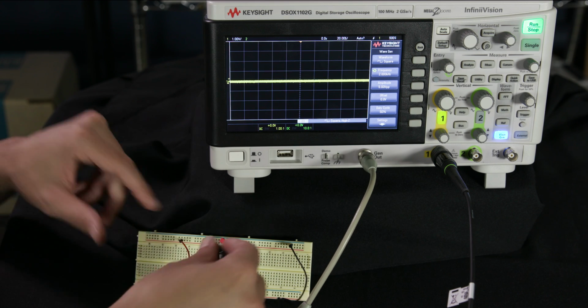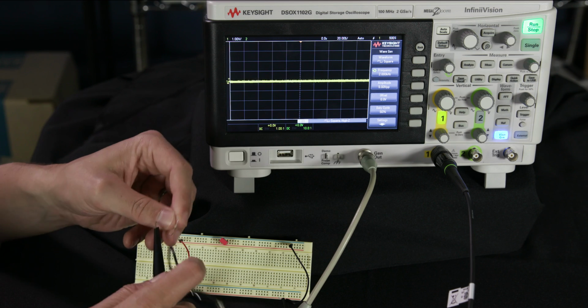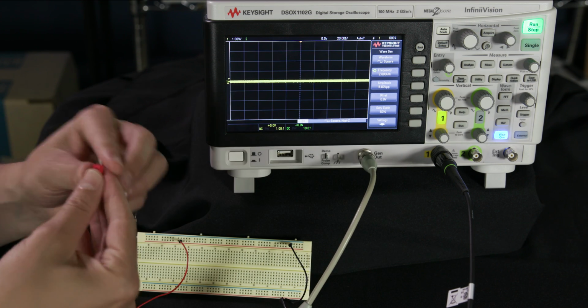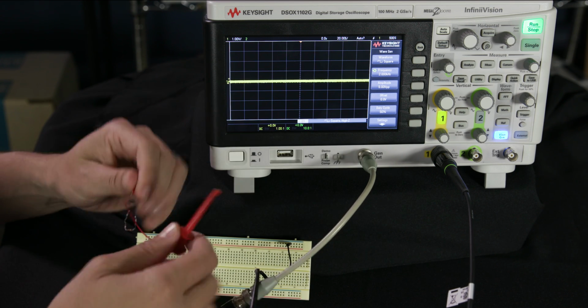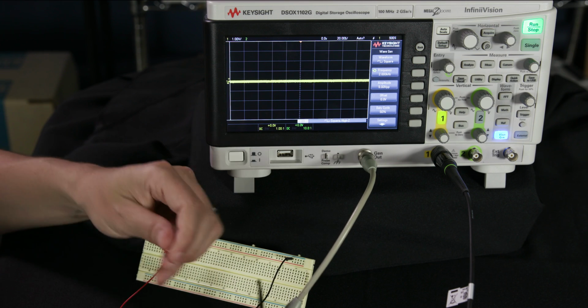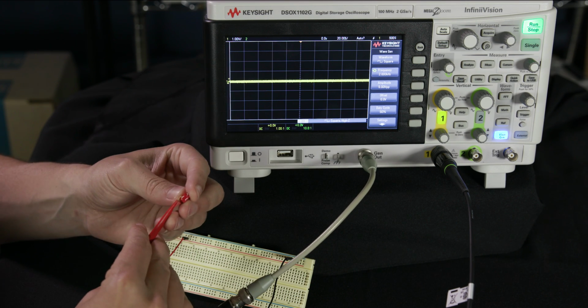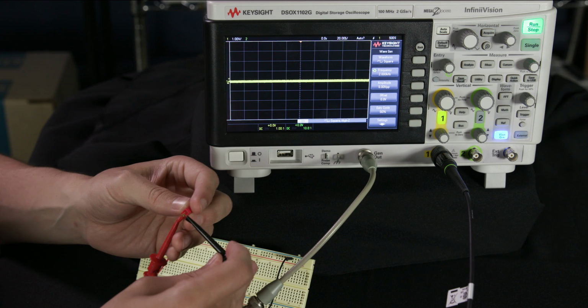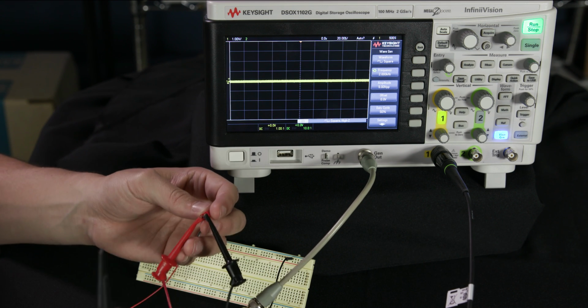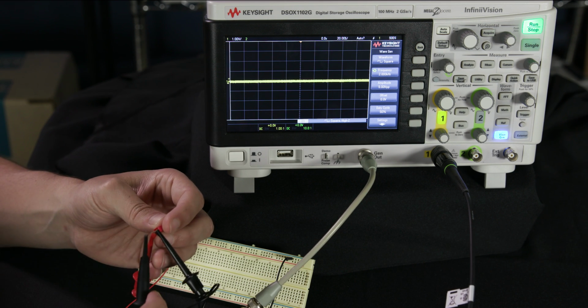So let's get rid of this resistor again, and let's remove these wires and just connect to the capacitor from the WaveGen. Now technically there's still going to be some capacitance in these wires and in the probe and some inductance also. That's just the nature of electronics as a whole. But that's something that I think we can drop out pretty significantly.